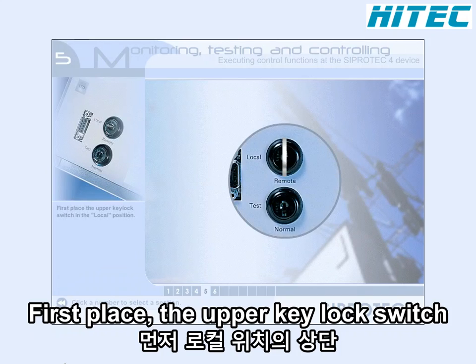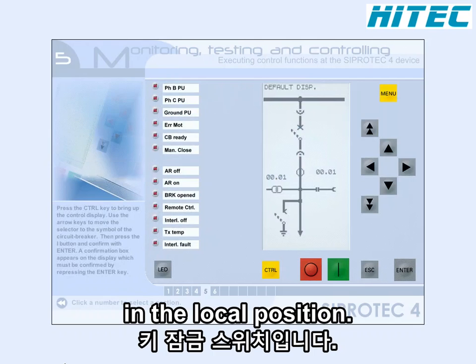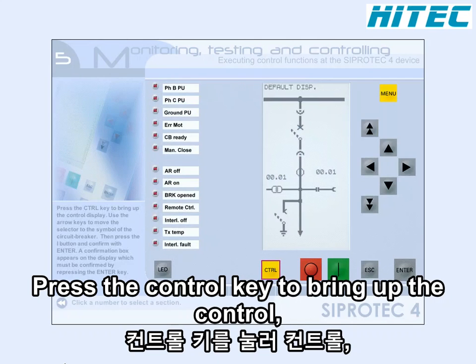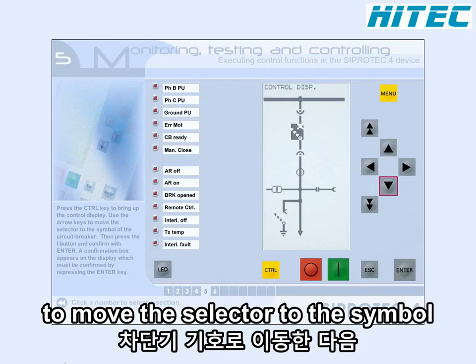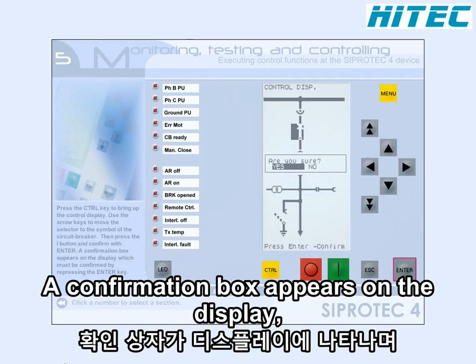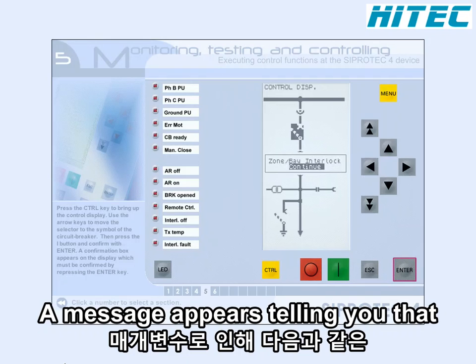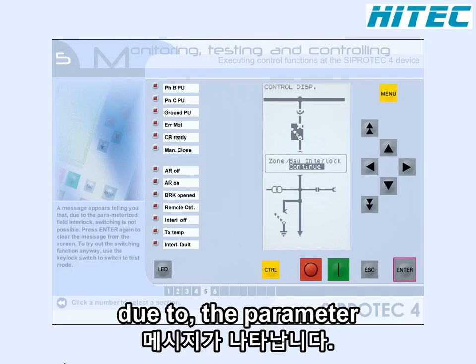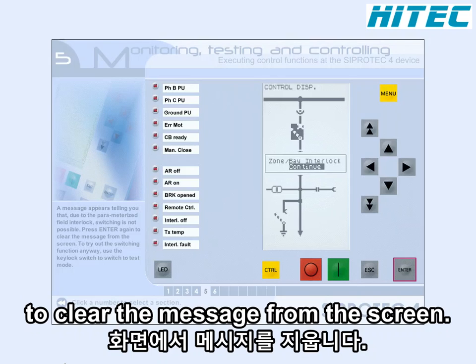First, place the upper key lock switch in the local position. Press the Control key to bring up the control display. Use the arrow keys to move the selector to the symbol of the circuit breaker. Then press the On button and confirm with Enter. A confirmation box appears on the display, which must be confirmed by repressing the Enter key. A message appears telling you that, due to the parameterized field interlock, switching is not possible. Press Enter again to clear the message from the screen.